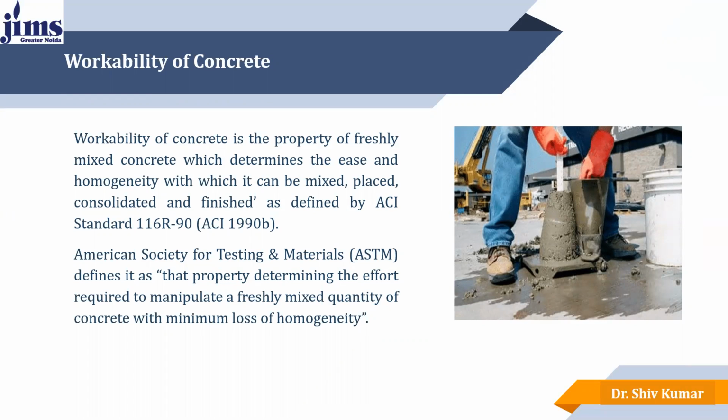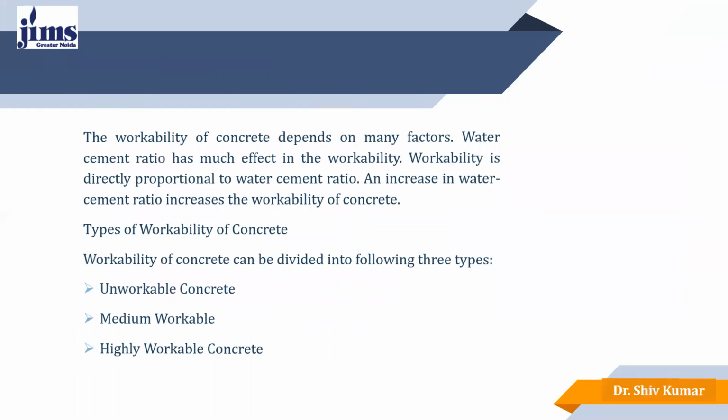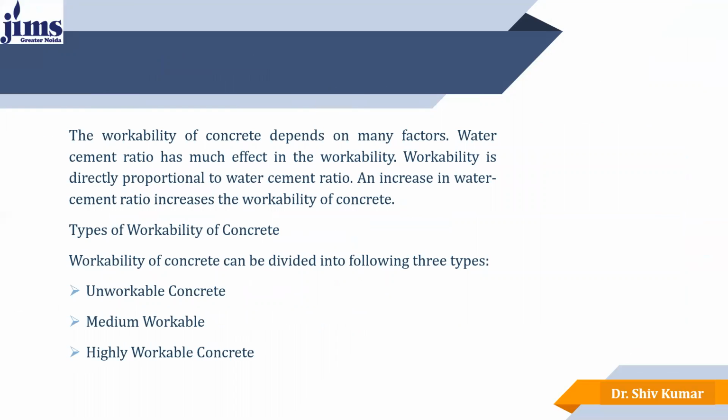The American Society for Testing and Materials defines workability as the property determining the effort required to manipulate a freshly mixed quantity of concrete with minimum loss of homogeneity. So it means when we place the concrete, it should be homogeneous in mass and self-compacting. It should be easy to place and easy to finish. This is the basic concept of workability that the American Society for Testing and Materials defines.